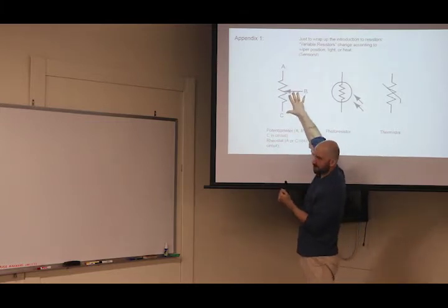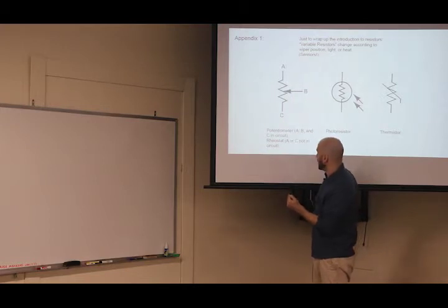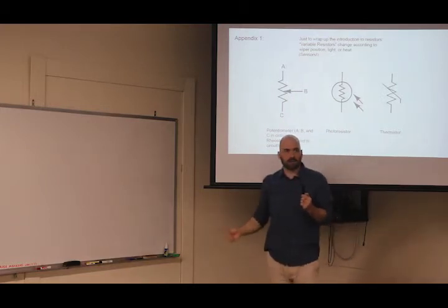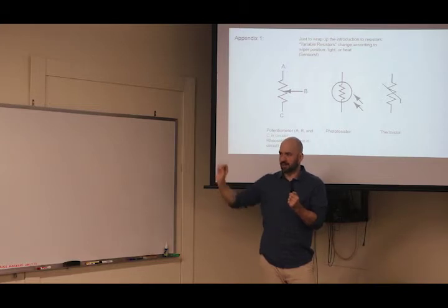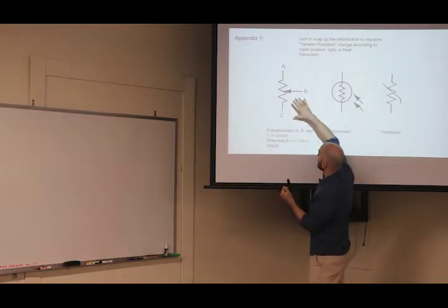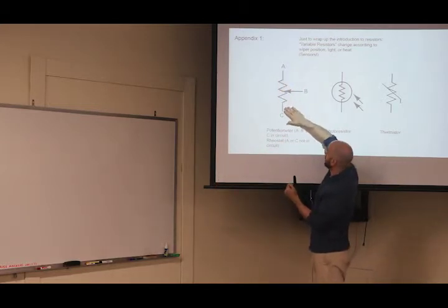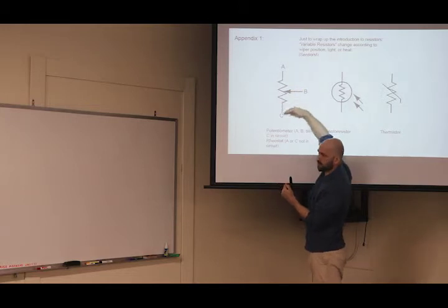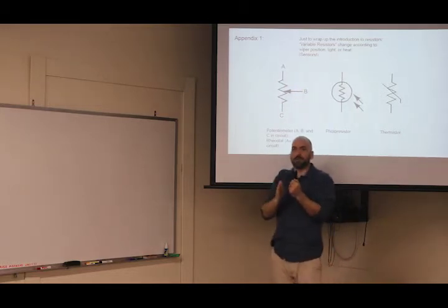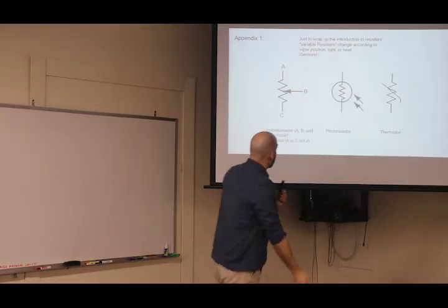A rheostat might only have 2 terminals to connect wires to. An example of where we've all encountered those is light switches where you can change how bright it is. You might do it with more complicated circuitry these days, but basically, if you turn the knob or slide the slider, what you're doing is saying, this resistor, I want to split here and only pass my electricity through this part of the resistor. You're varying the resistance that way.